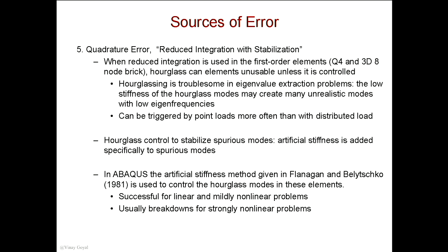Yeah, so let's say you run it and you do get shear locking, but you don't know it. If you wanted to confirm that easier, would you just increase the number of elements? Yeah, absolutely. You want to do a mesh refinement study to see if you got shear locking. Another thing you can do is hand calculations. There's something simple you can always do. For example, I think somebody here ran, did you guys do problem number 2? From here. Yeah? Does it move at all? Not much. With triangular elements? I don't think this moves. You apply loading, it doesn't move.